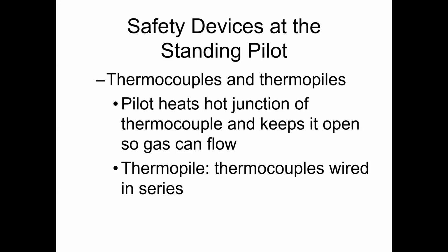Problem? His thermocouple. His thermocouple was not operating and was not picking up a signal from the flame. Reason? Too much soot on it. Well, I charged him $500 to go clean all that soot and everything off that. Did it take me that long? No. Was that the thing I'm supposed to do?